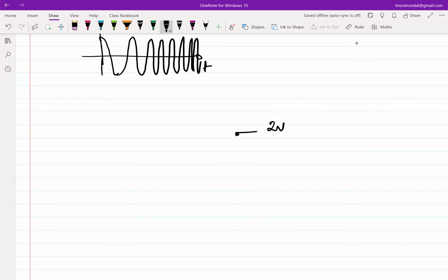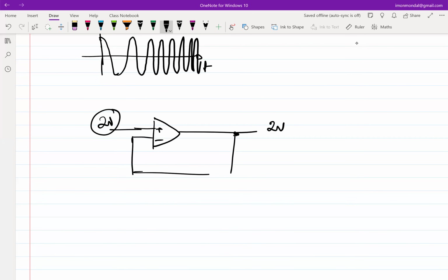You will use negative feedback, right? So what do you do when you use negative feedback? You take this 2 volt and then compare it with something. What are you going to compare it with? 2 volt. And who generates this 2 volt? Some reference which comes from outside. So you have shipped off your problem to somebody else, right? Give me an accurate reference, I'll give you on-chip accurate 2 volt, right?